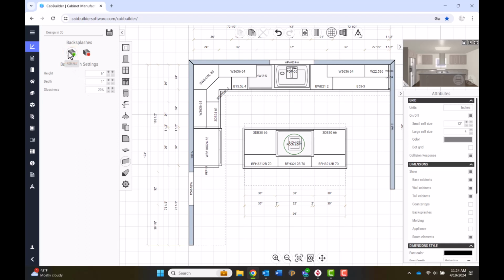Finally, add the moldings. Click the icon on the right of the panel that appears as a long piece of molding material. Here, you will need to place a mark to the left of each molding you wish to apply, or unmark a molding option if you do not wish to place it in this design.